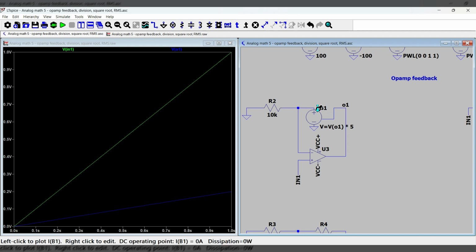Well, if you look at a perfect op amp model, what it's doing is in steady state, both of these terminals have the same voltage and they have no currents. So you can actually run a KVL on this loop, and you can see that whatever transformation goes from the input, because this is the same voltage as the input, to the output has to be the reverse of whatever's happening up here, going from the output back to the input.